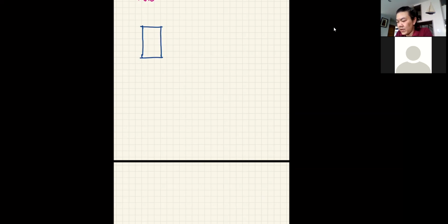So let's say this is the width B and this is the depth D. Now for the elastic, let's calculate the major axis, which is X. The Ix is going to be equal to BD cubed over 12.